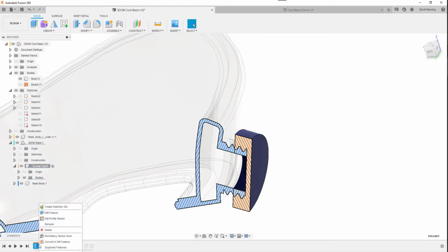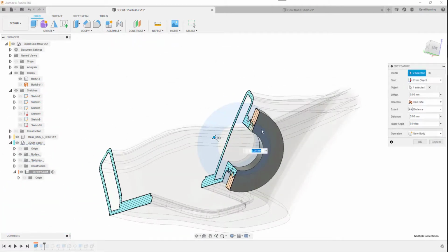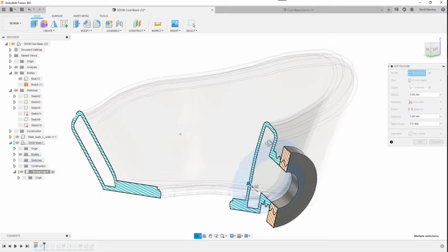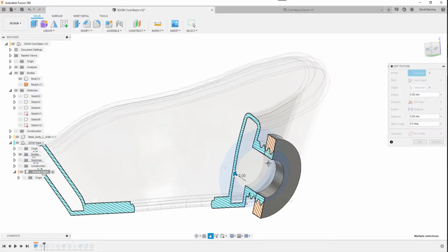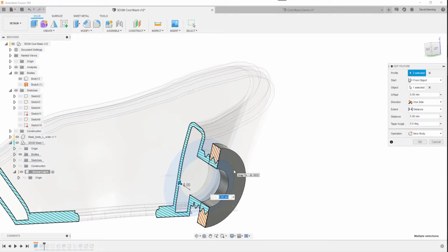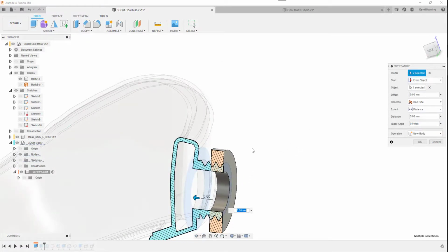What we want to do is we extruded first, we picked the thickness we wanted, so the main part of the body, but we're going to add the thread to. You don't have to pick this in a ring because the thread will adjust that body to suit, but I chose to at the time. Extruded that 5mm, and I chose to pick the start plane from the end of the thread body, and then project it 5mm down from there, which is going to give me a 5mm thread depth.